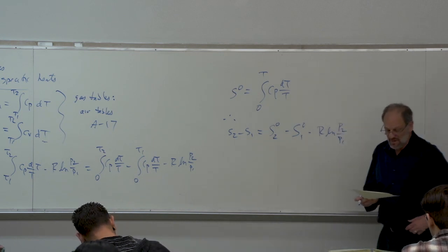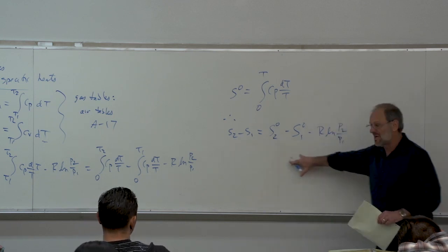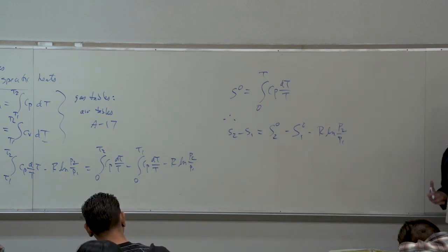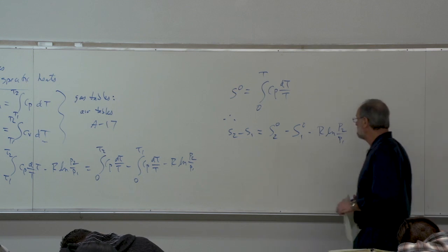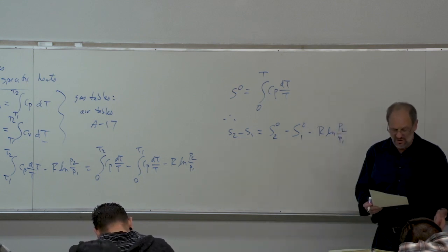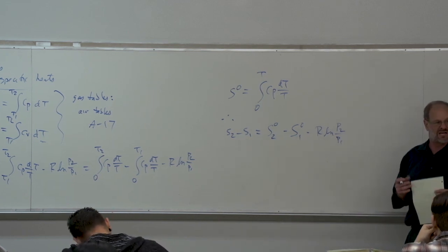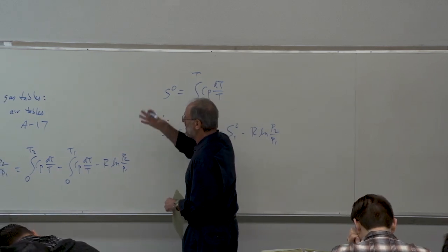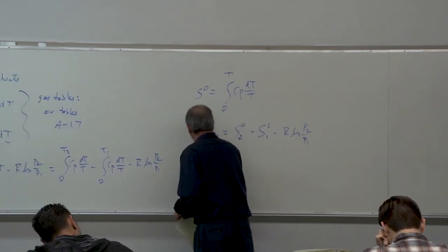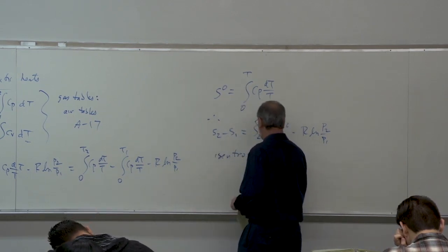the pressure ratio. So this is an equation that we may need to use occasionally as we're trying to find an entropy change for a process that involves an ideal gas that is considering variable specific heats. Next, what I would like to do is note that in many, many cases, we're interested in analyzing ideal, or if you will, isentropic processes. So continuing with ideal gases and variable specific heats, what if we have an isentropic process?